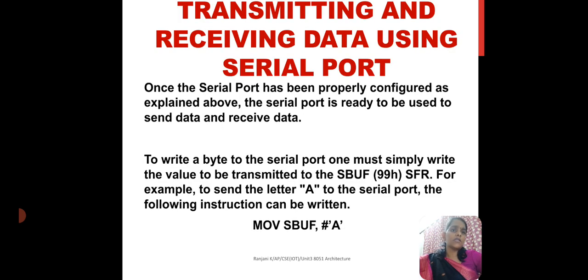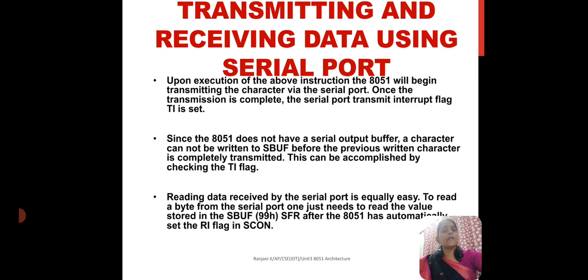Next is transmitting and receiving data using a serial port. Once the serial port has been properly configured, the serial port is ready to be used for sending and receiving data. Whereas the 8051 does not have a serial output buffer, a character cannot be written to SBUF before the previous written character has been transmitted.